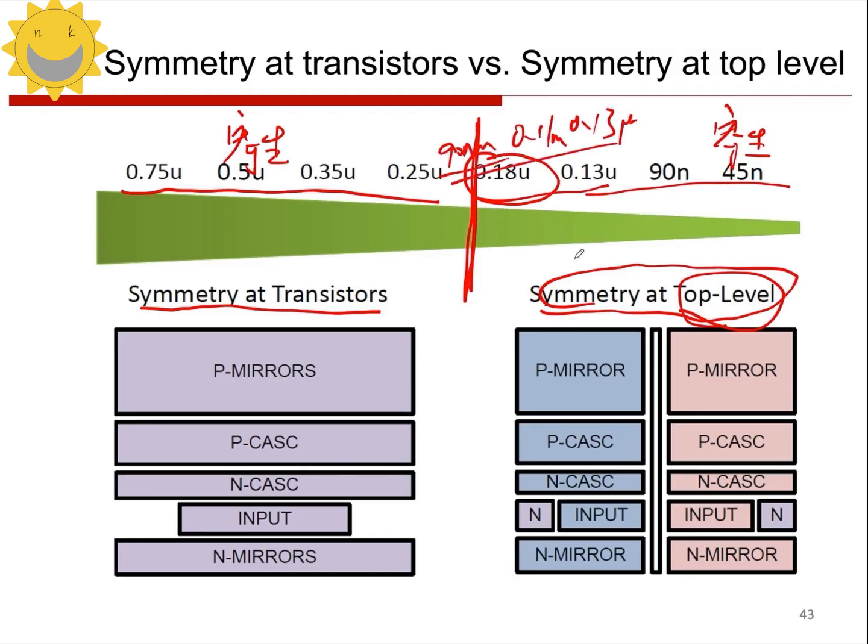So, where are the critical areas? For example, the input differential pair, right? The input differential pair, along with our p-type current mirror and n-type current mirror. For these three, we might use the common centroid method, or to simplify, we might only use the common centroid for the input differential pair, right? The input differential pair is more critical. We use the common centroid for the input differential pair, and for the rest, we might just use top-level matching. This way, we can achieve a good balance. It's about using a combination. You achieve the best compromise between matching and parasitics. How do we choose this matching strategy?